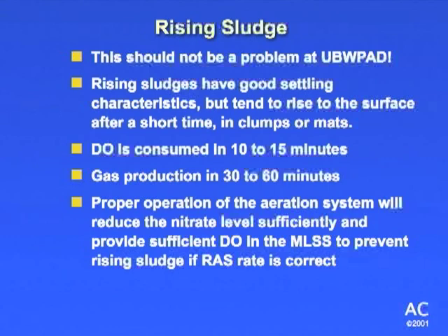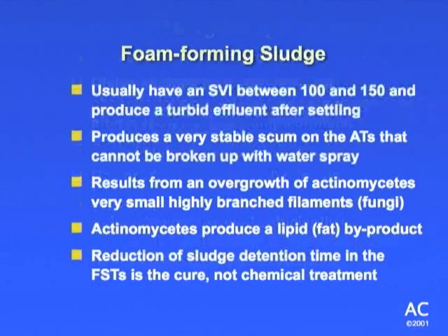We're not pulling too thick where you're letting it sit too long, or you just return it ridiculously fast, okay? And again, that's why we're looking at a return rate initially of 69% of the average daily flow of your primary effluent. Then you've got foam forming sludge, and again, SVI is very plant specific,